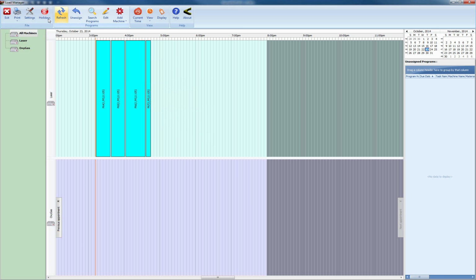Using schedule and holidays, you can view times, you can view users that are logged in here as well, and even search programs. If you actually open up a program, you can see the sheet name that's used, and you can even see what parts are being cut on it. So it's a full Gantt chart that's interactive, and you're actually posting out as you're dragging and dropping them, and you're planning them out on the floor. So there's a lot more power to this as well.